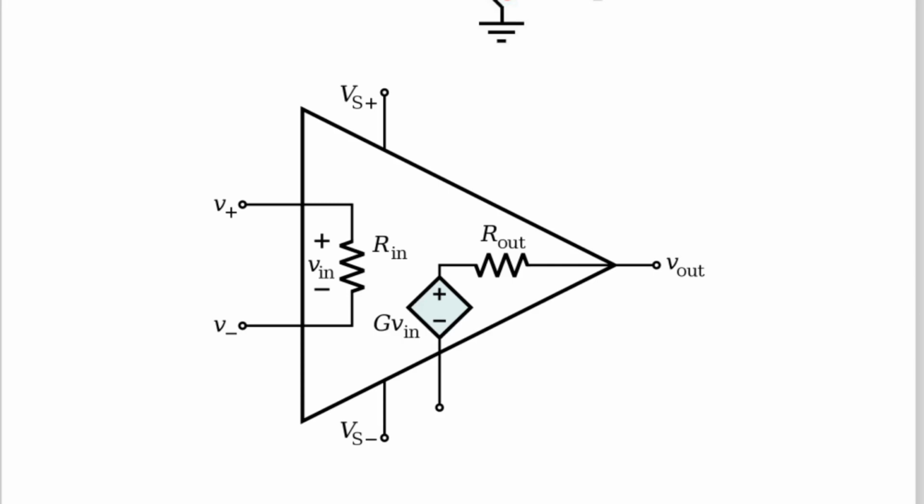The equivalent circuit diagram of the OpAmp is in between the inverting input and non-inverting input. In between the inverting and non-inverting input, input resistance is offered by the OpAmp, meaning the first block of the OpAmp, that is called the dual input balanced output differential amplifier, and that input resistance is marked by Rin. Then the last block of the op-amp you know very well, that is the amplifier. So the amplifier is as good as a source of voltage. So this source of voltage is marked as plus and minus. And Rout is the output resistance offered by the op-amp. So that is called Rout.